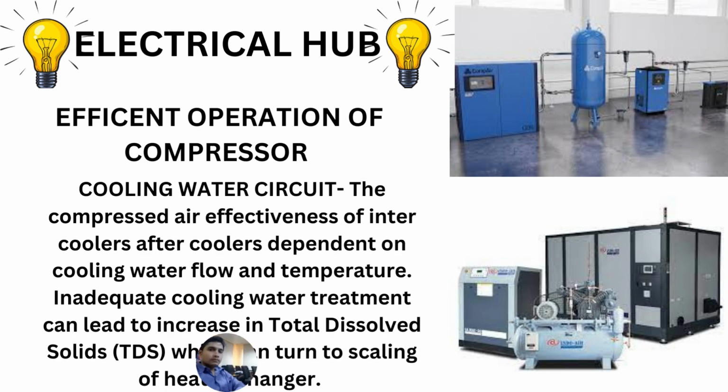Cooling water circuit. The cooling of the air in the interstage or the aftercoolers depends on the quality of the water, its flow and temperature. Inadequate treatment of the water can lead to an increase in the TDS, that is total dissolved solids, which can turn into scaling of the cooling area.